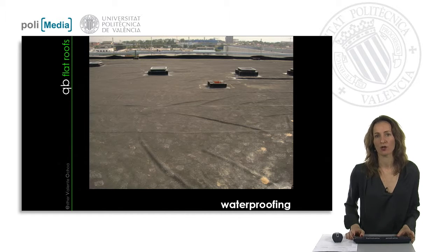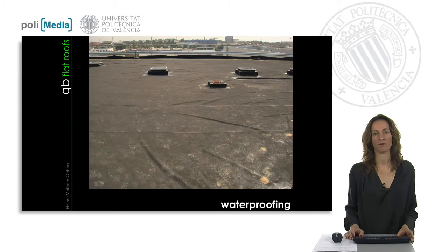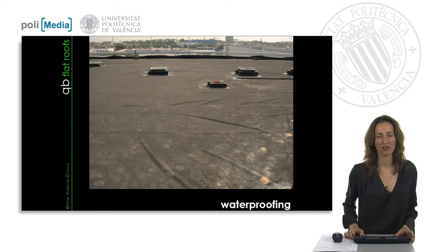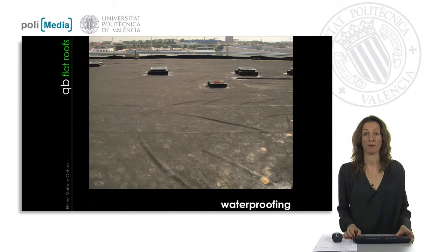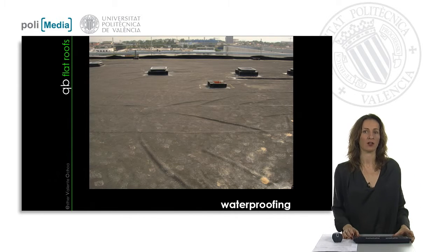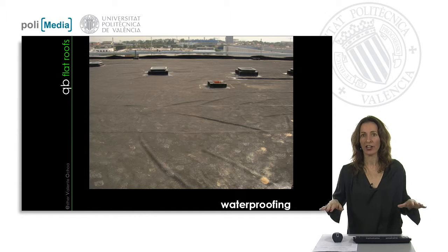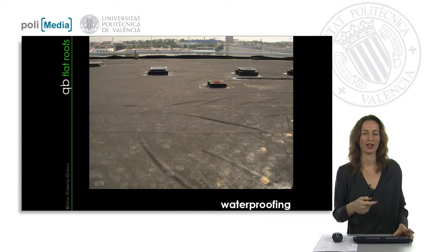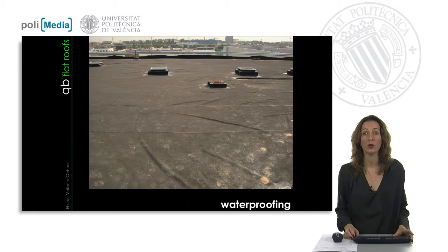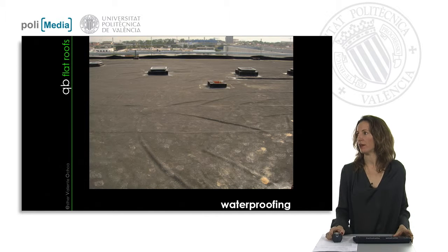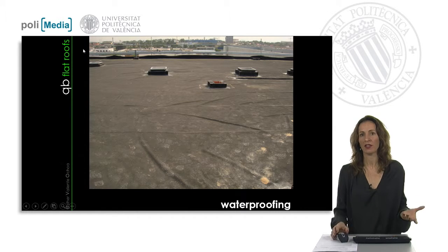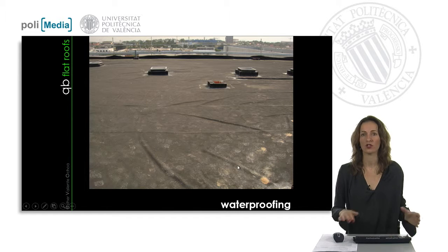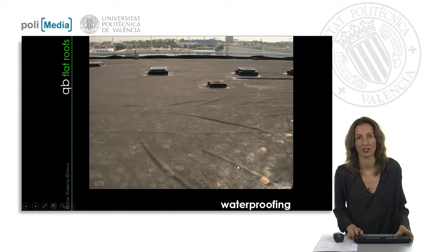This picture is showing us an EPDM sheet. This sheet is self-sufficient, a very good quality barrier sheet that protects the building. But the way to fix it on the cover is completely different. It's loose, it's not fixed. Only the boundary areas are fixed with a special resin that glues and joins this sheet to the whole surface. Only the building services areas and the boundary are fixed. The intermediate area can have this kind of bubbles because it's not fixed in the middle.